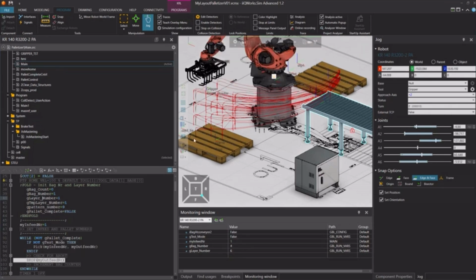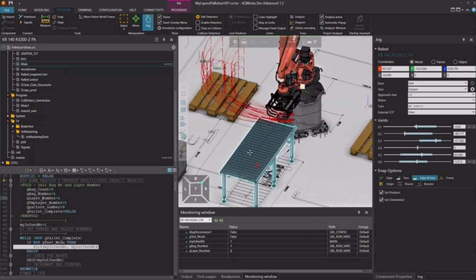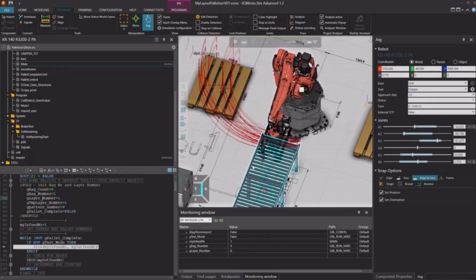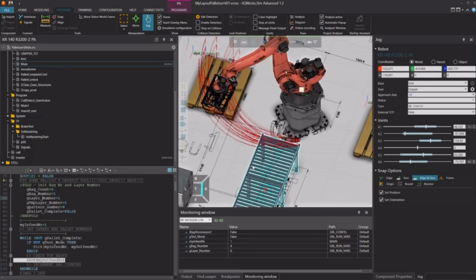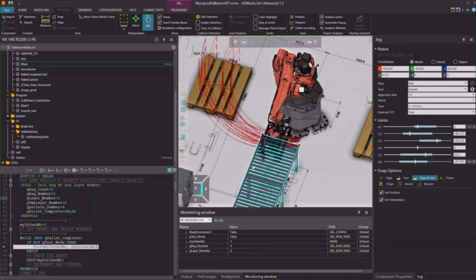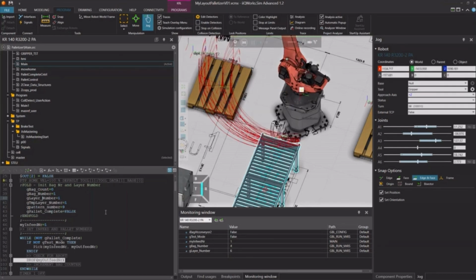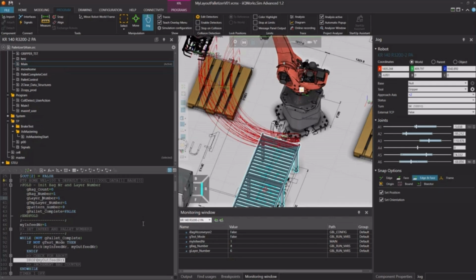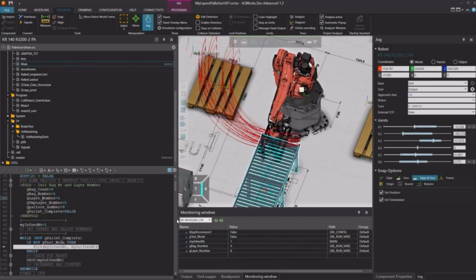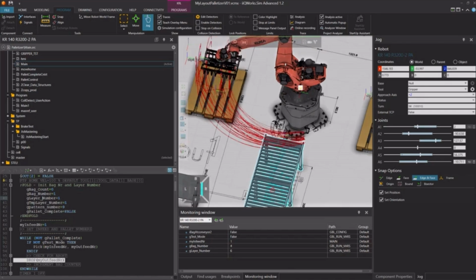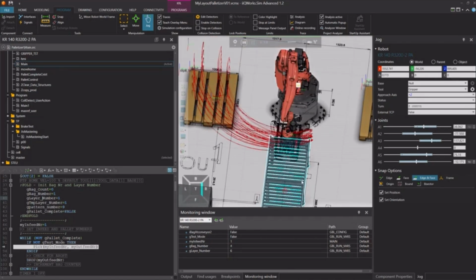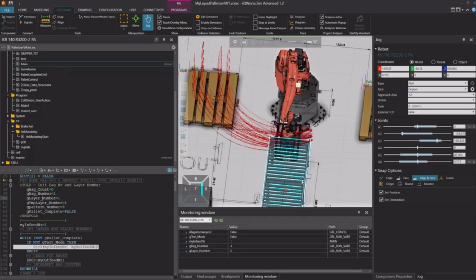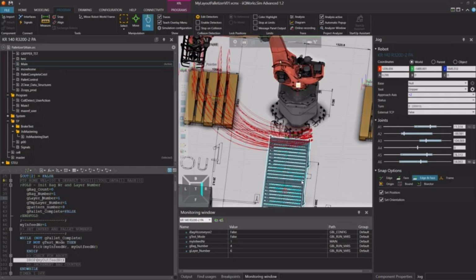Additional global variables such as bag number and layer number are monitored. This confirms that the palletizing logic is progressing through layers correctly. The most important takeaway is how to migrate config.dat data, including tools and bases, from older systems. Converting systems from KSS 8.6 or 8.7 to iiQKA.OS2 is very achievable with these steps.